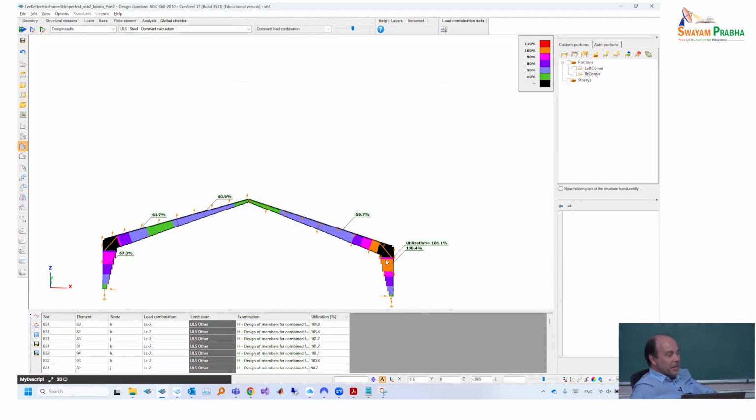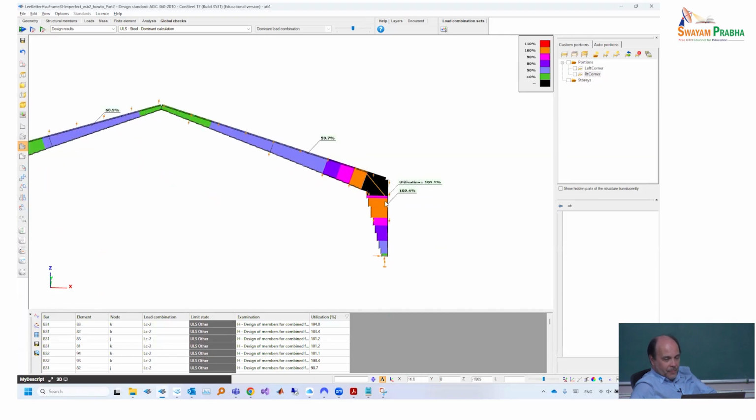So all the things we do have an impact on the slenderness. We have improved the slenderness calculation, which improves the LTB strength calculation. But as long as the local buckling remains the controlling one, actually it makes no sense, what we do. Flange local buckling, hint, hint, hint. What do you do about it? Okay. Now there is one other thing, and then we are at the end of this part of the demonstration, and then we can start to explain what the exercise will be.